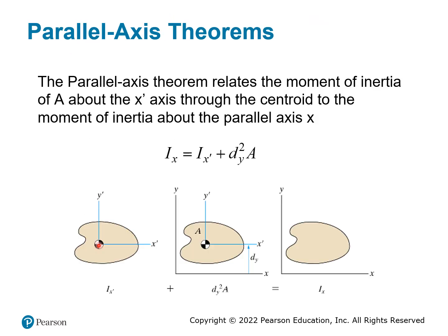So to give you a summary of this one here, I'll show you why this Ix is equal to this one. This is what we call the centroid, the center of the moment of inertia, and we use Ix with a bar to represent that here. If you add the total area and multiply it by the distance of the parallel axis squared, that will be equal to the moment of inertia. That is this one right here, and this is the parallel axis theorem.